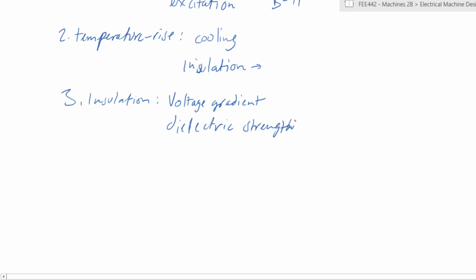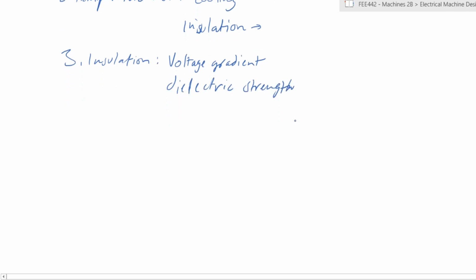So for example, if you have very high voltage applications that you're dealing with, if there are generators for mains operating at 11 kV, you must design accordingly. If there are low voltage motors, small DC motors, you can also design your insulation to be lower than what would be required for a high voltage application. That has economic considerations, that has weight consideration, and that has practical manufacturing considerations. Number 4 is mechanical strength.